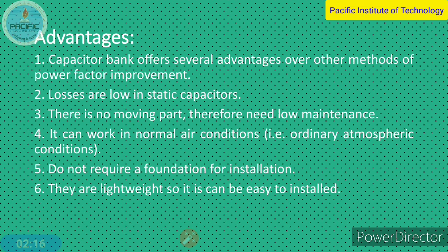Now there are certain advantages and disadvantages of using a capacitor bank. The very first one, we will discuss the advantages of using a static capacitor bank for improving power factor. The losses are low in the static capacitor. There is no moving part, therefore it needs low maintenance. It can work in ordinary atmospheric conditions and does not require any foundation for installation.